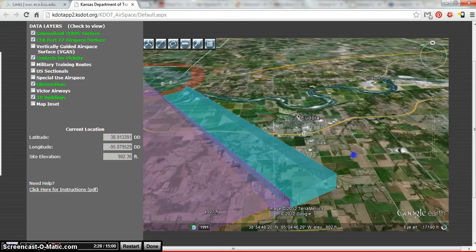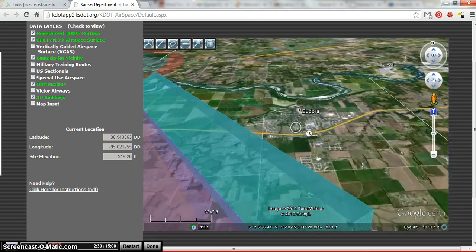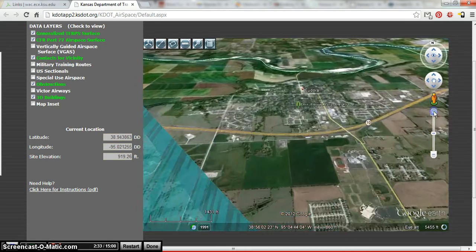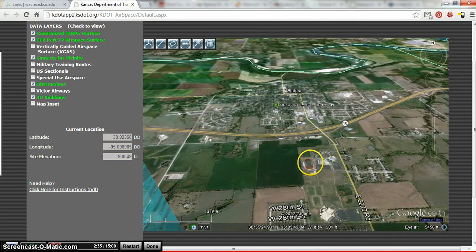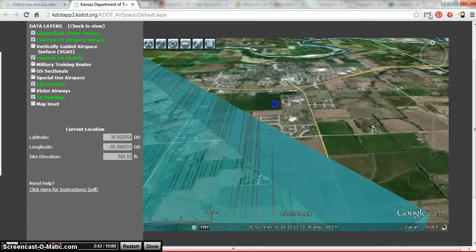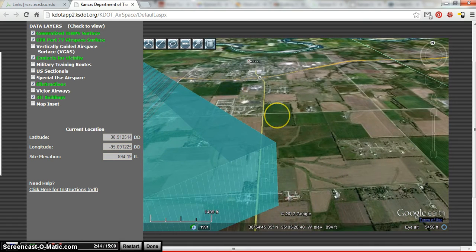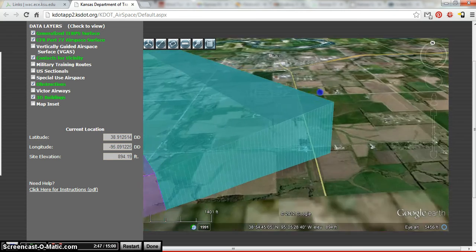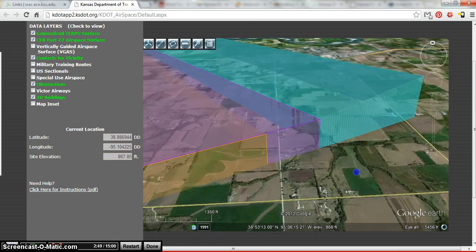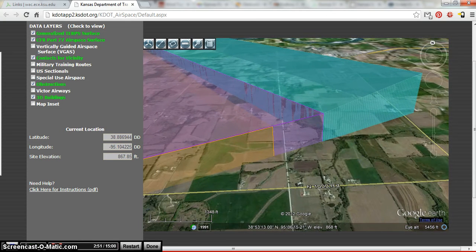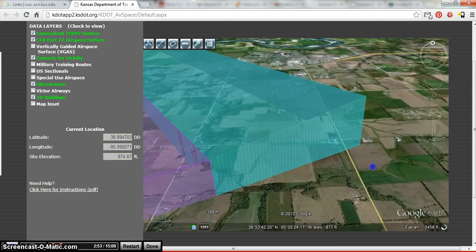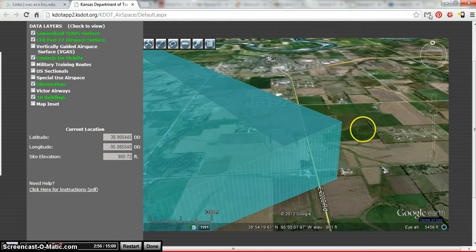As I then navigate a little bit closer towards the city of Eudora, you can zoom closer down here and start seeing the idea of the football field within our Eudora High School campus and the location for our wind turbine where it actually sits. You start seeing the wedges that lead up to that with the TERPS surface that I mentioned earlier, as well as the 77 airspace, and where the safe regions are, as well as where additional requirements would be mandated by FAA regulations.